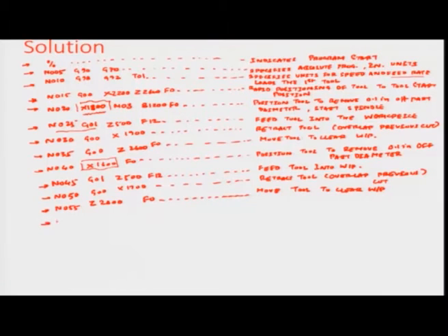In the next step again we will have the finish cut. So, here we need to go to X equal to 1500, corresponding to a 0 feed again. 1500 makes sure that we have a finish machining of 0.05 inches deep, that means 0.05 inches on the radius or 0.1 inches diametrally, from the 1600 position that we had hit upon in the last step.